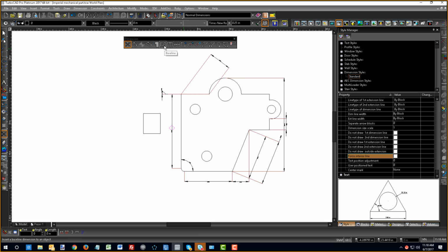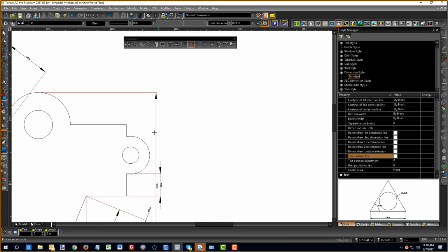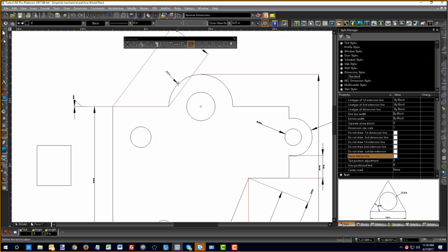Okay, and then the radial and diameter snaps, even if your snaps are on, they just aren't required. In fact, they won't even really work. I can prove that by turning snaps off completely, and you'll see that the radial and diameter dimensions automatically seek out the arc angles or the circular objects, and will work automatically on those.